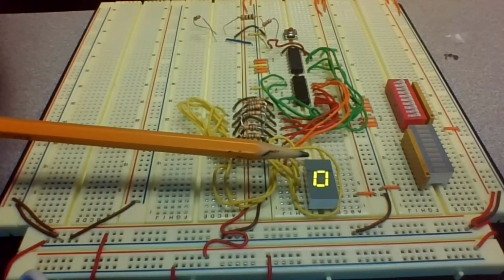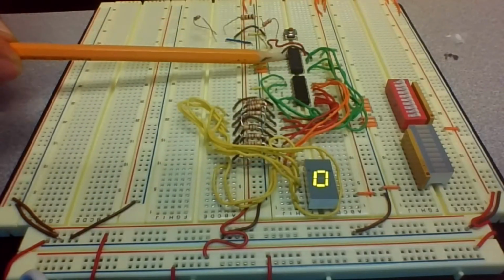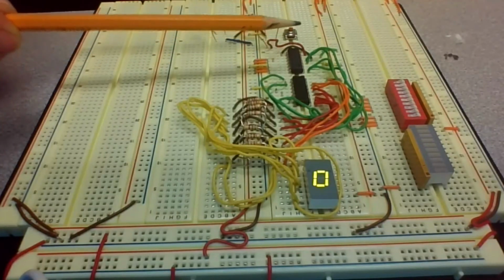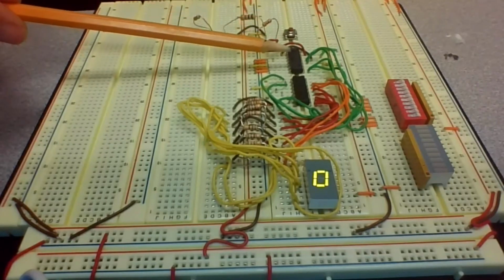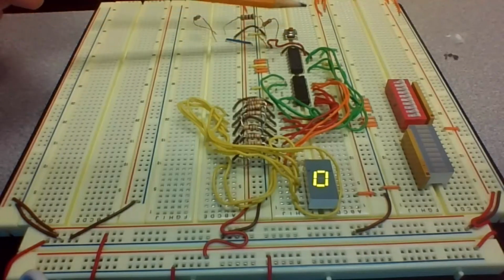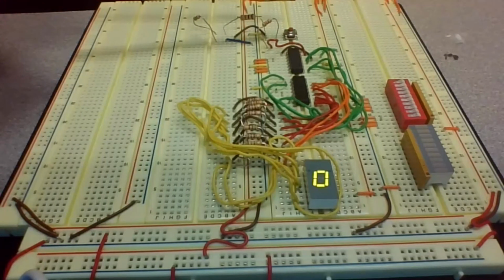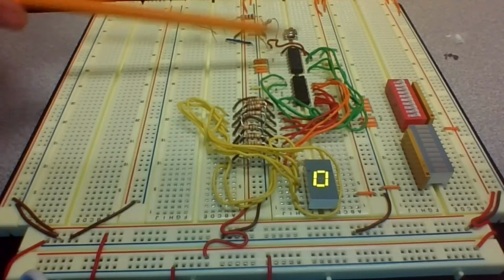Okay, so this BCD counter is sensitive to the falling edge, so we connected the clock pulse of this counter to the switch. Whenever we push the switch, it actually gets 1. Whenever we release, it moves from 1 to 0. This is sensitive to the falling edge. That means whenever you push the switch, it gets 1, and whenever you release, it gets 0. So whenever it goes from 1 to 0, the counter starts to count.